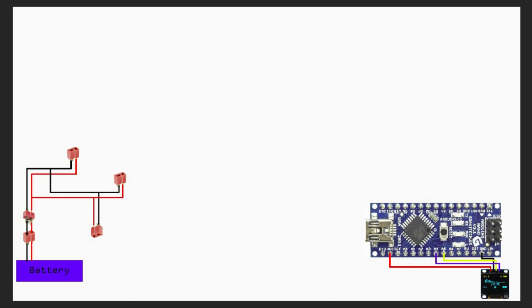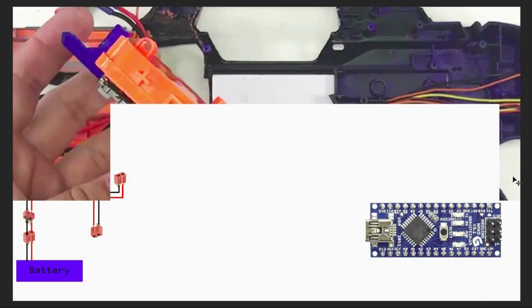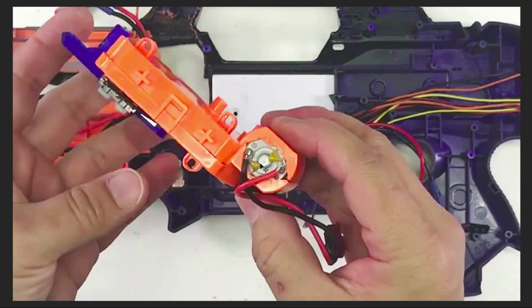Oh yes, I talked about the pusher. Now, if you want to clean the signal and you don't have the capacitor plate, you can buy this kind of capacitor itself, and then solder it to the terminal and then to the case of the motor itself. In my previous video, I also linked to the article whereby they talk about how to clean the electronic signal for this sort of application.